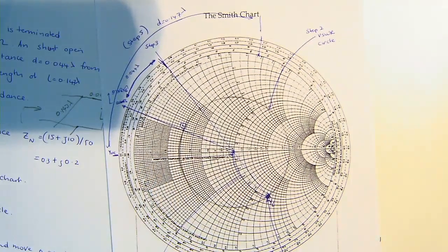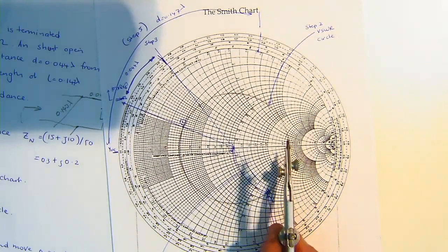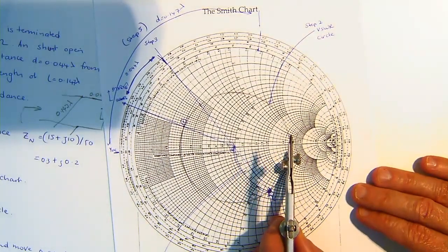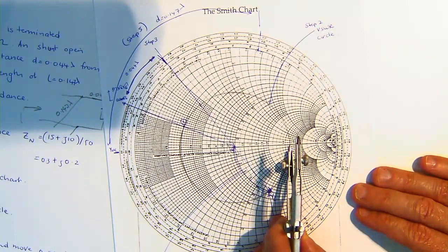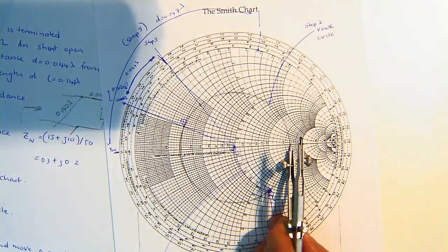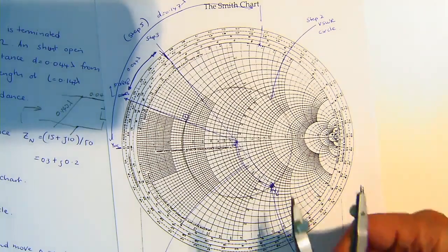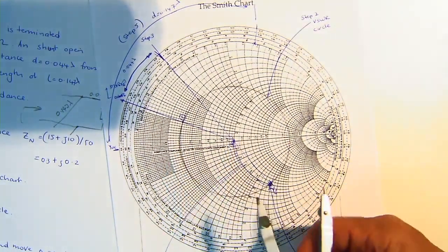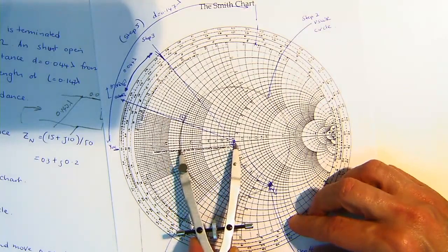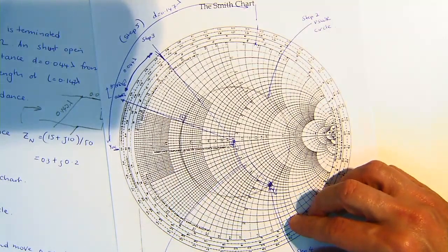All right, what's the maximum impedance? Yeah, around 3.4. So 3.4 times 50, which is 170 ohms. Perfect. So we know what the minimum and maximum impedance is. What's our voltage standing wave ratio if I'd asked you for that? Perfect. All right, okay. Done. So we said it's here. So we'll work it out here, and it's roughly 3.6.